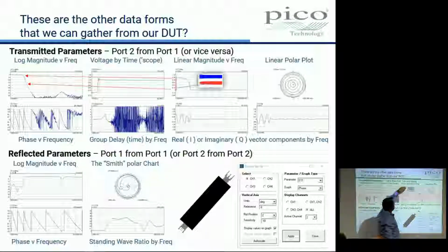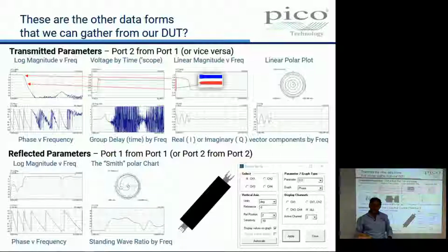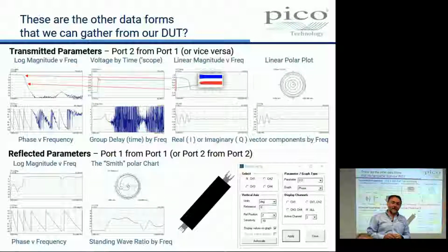This is what happens for this DUT. The linear gain goes on, it falls away gradually, and then it comes to, what's this? It's about 700 megahertz or so, and it goes whoa, off a cliff. Yeah? And so that is our equivalent to our scope network analyzer.